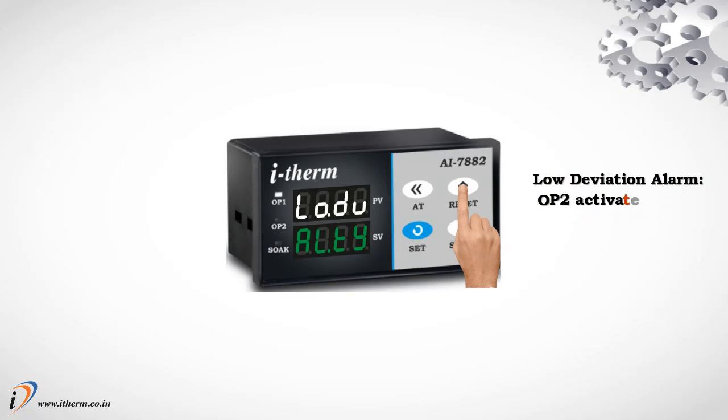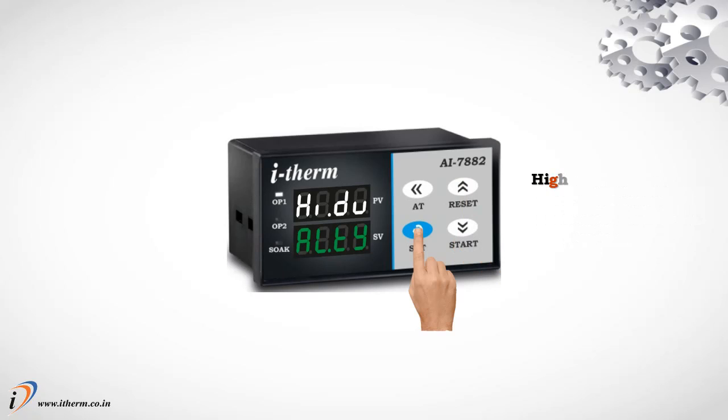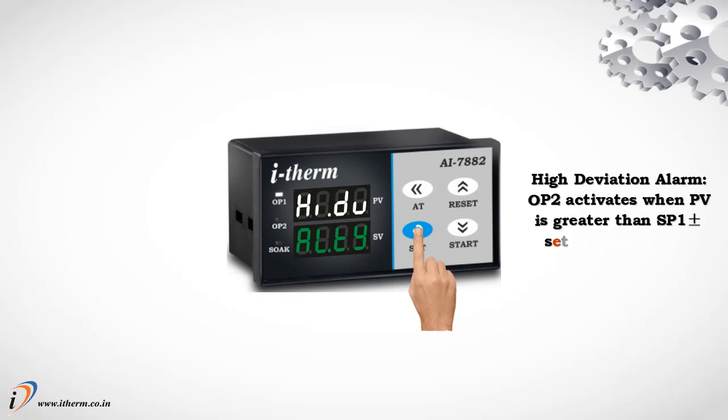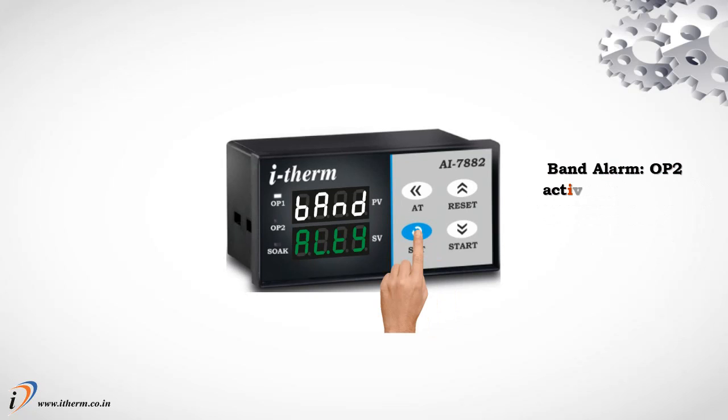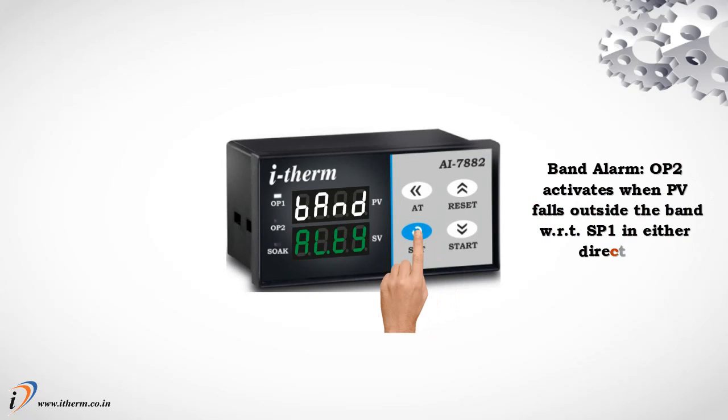Low deviation alarm, output 2 activates when process value is less than setpoint 1 plus minus set deviation value. High deviation alarm, output 2 activates when process value is greater than setpoint 1 plus minus set deviation value. Band alarm, output 2 activates when process value falls outside the band with respect to setpoint 1 in either direction.